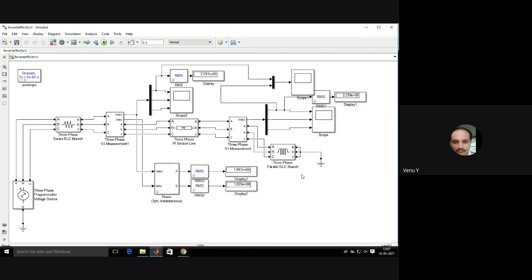So this is about compensation with reactor. The small deviation may be controlled with the control reactance, and particularly this reactor is suitable for no load only. If you want to change the load from no load to 1/4 full load or small load, it may give different results. Therefore, in order to provide effective control over the transmission system, you need to go for a thyristor controlled reactor.